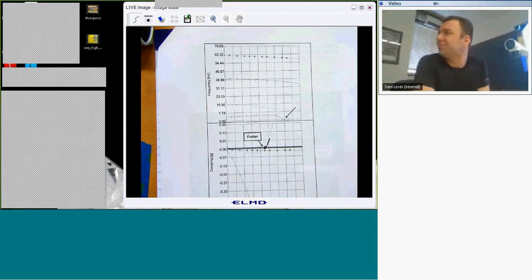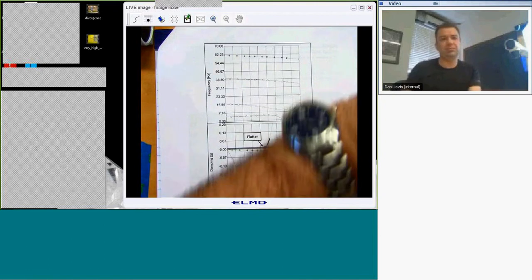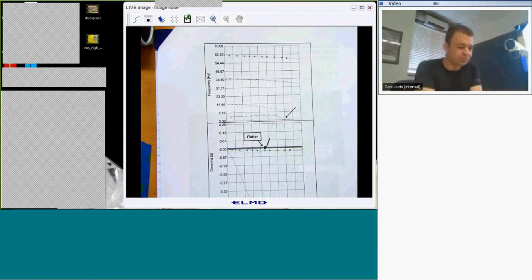The other thing to point out is that the structural modes are the modes that exist when the velocity of the flow is zero. When the velocity of flow is zero, you have certain natural frequencies of the structural modes, and the damping is zero in all those modes unless you've assumed some amount of damping in your structural model. But once the airflow exists and you change the velocity, you have aeroelastic modes which have aeroelastic eigenvalues as both the frequency and the damping.